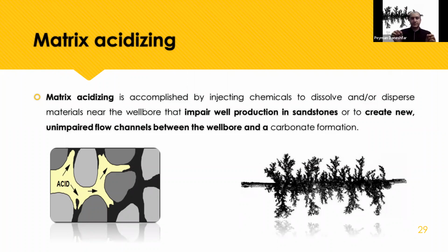But remember, this is important that I want to tell you. For the skin factor in a sandstone reservoir, when we use matrix acidizing and inject the acid into a well, our skin factor decreases at most to 0. It means that the well comes back to its past production.